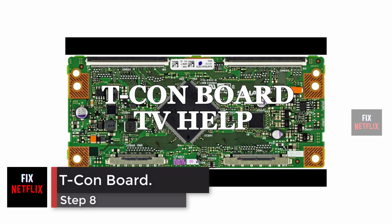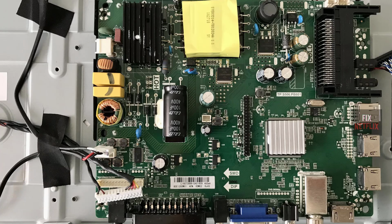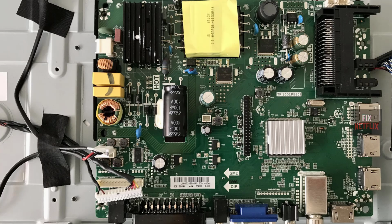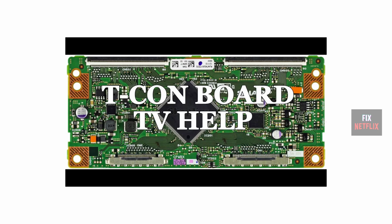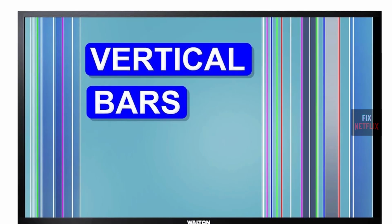Step 8. TCON board. This check for the TCON board also touches on the condition of the main board. Note that problems that show up on half of the screen, like bars or such, point to a failed main board, as the TCON board errors show up on the whole screen. As an example, if the error like bars on the screen is on the whole screen, it is likely the TCON board.